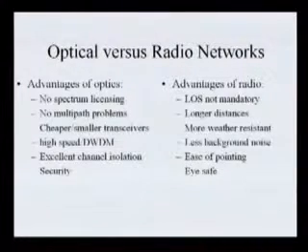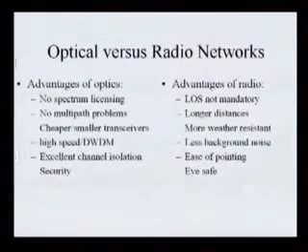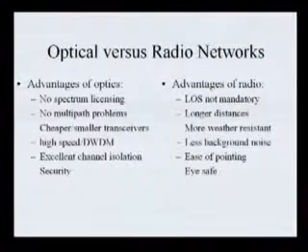That frequency band is totally unlicensed, 57 to 64 gigahertz, and you get 7 gigahertz of bandwidth. But the problem with that particular band is that you can't go very long distance. You can go about 1 kilometer, and that's about it. But for our campus, 1 kilometer is really almost reaching from the north to the south part of the campus.